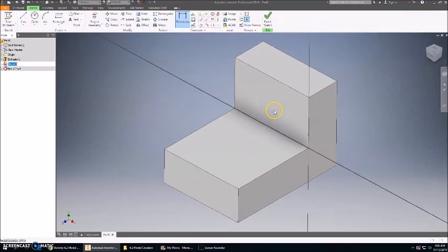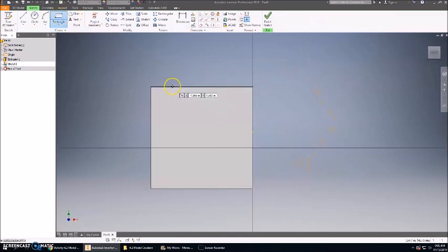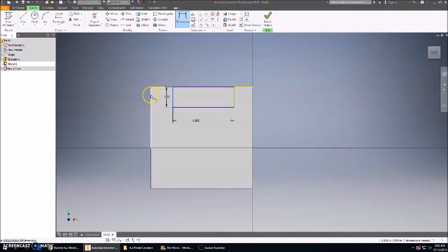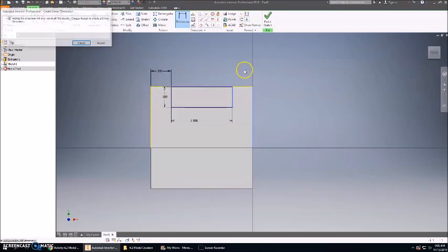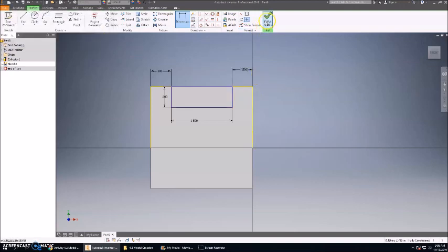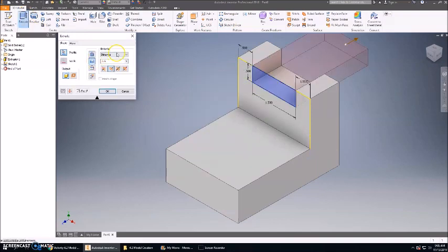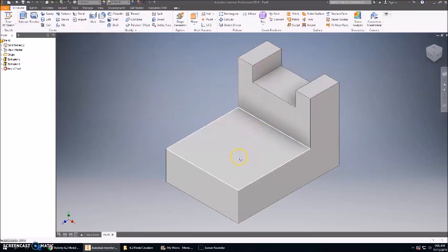And now I'm going to put my new sketch up here to do that subtractive portion. So I'm going to grab my rectangle tool and I'm again going to constrain it to that top line so that way it stays locked to that top edge. And then the depth on that is 0.5. Right here we have 1.5, and I think the distances between these two edges are 0.5. So I'm going to go here to here, change that to 0.5, and then this one, if I try and dimension it, is going to appear as a driven dimension. No big deal. So we're going to hit Finish Sketch. I'm going to choose Extrude. I'm going to click that area, change it to Cut, and change my distance to All, and then click OK. So that top portion is complete.